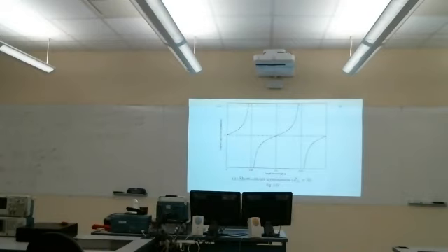Often we could do that with some combination of inductors or capacitors. But there's something interesting here. When we look at the input impedance with the open circuit, and we'll look at the short circuit case first, you can make a piece of transmission line look like an inductor or a capacitor.